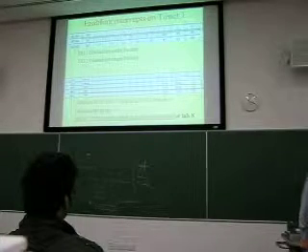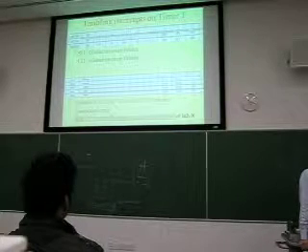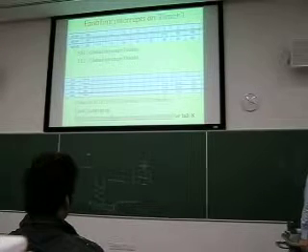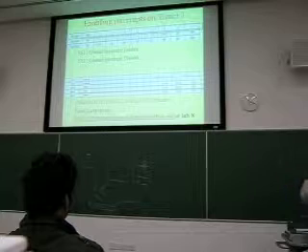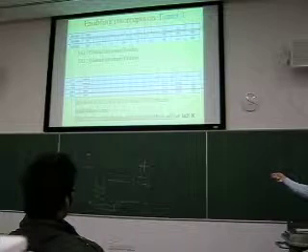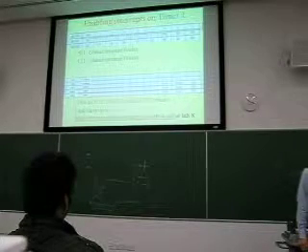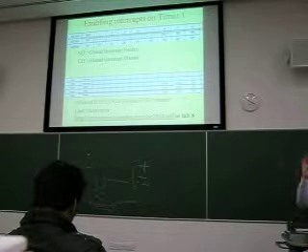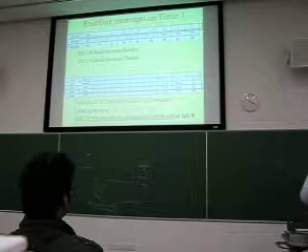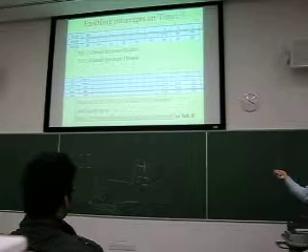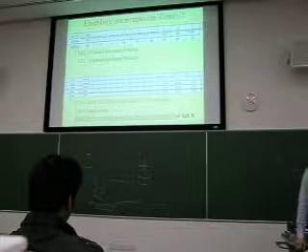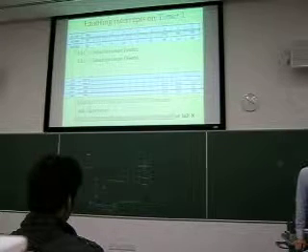Sorry? Yes. It's to do with the interrupt or the overflow of the timer. So when the timer overflows, it creates an interrupt. Then you set it to 1 if you want this kind of interrupt to happen. Whereas these two are to do with the compare interrupts. So if the value of my timer matches the value in register B, for example, then it creates an interrupt. For this one, it is for register A. And this one is for the input capture interrupt. You need to enable it.